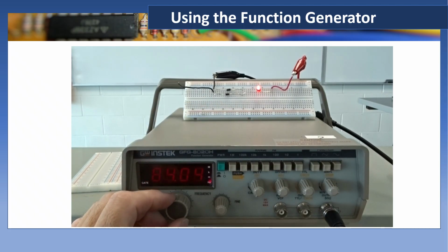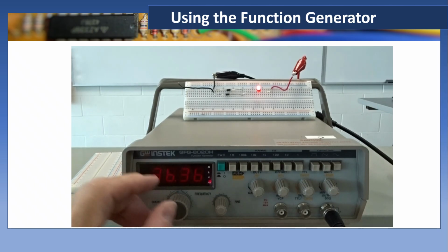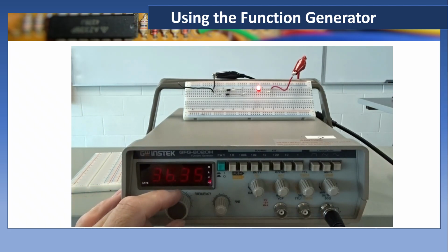We're at 100, we're going to drop it down and see where it just starts to flash, where it's discernible that it's flashing. Below 60. And it's starting to kind of vibrate at around 36 hertz. It's getting more pronounced down at 27. All the way down to 18, 16. And now you can see that there's definitely a spot where it's almost completely turning off.